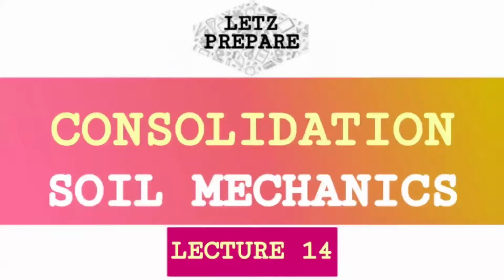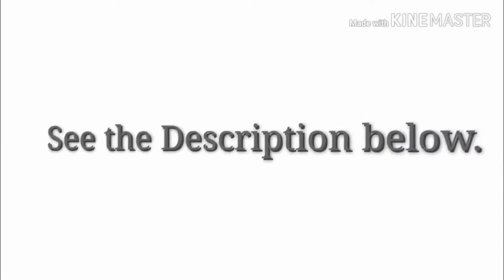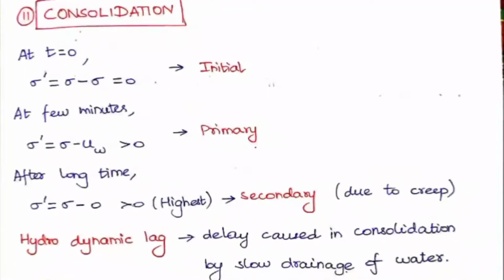Let's prepare on the consolidation of soil. Before going into the topic, let us see what consolidation means. It is just a compression, but due to the expulsion of water from the soil. If we take water out of the soil and compress it, we call it consolidation. If we are removing the air alone from the soil, we call the term compaction of soil.